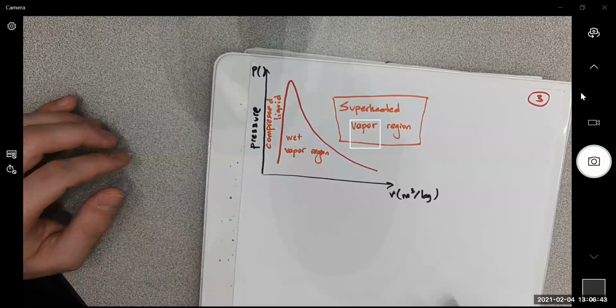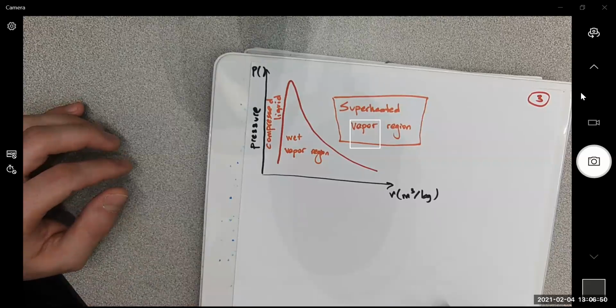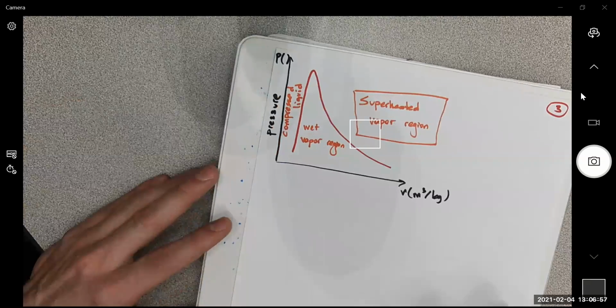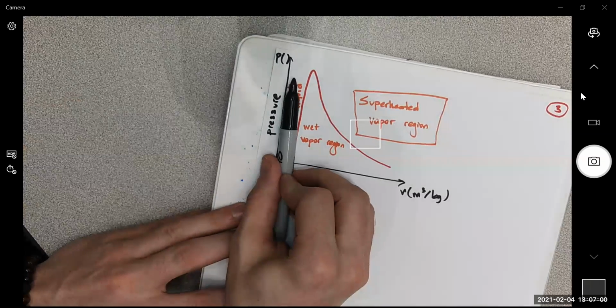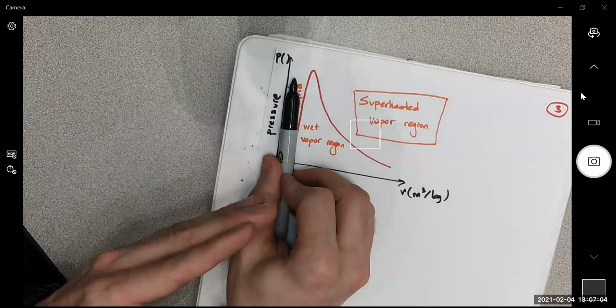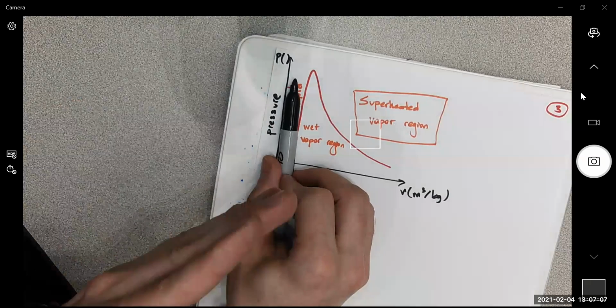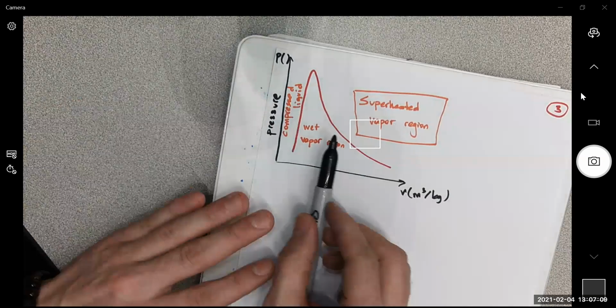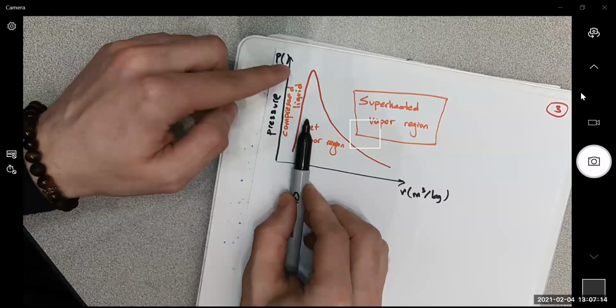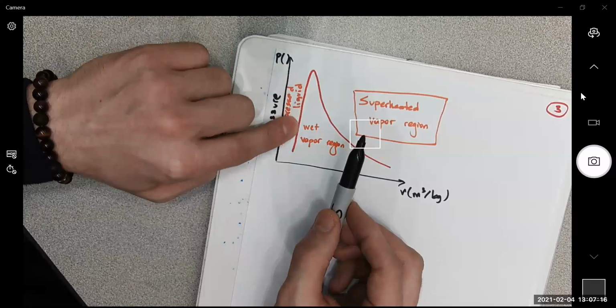So when comparing that with the linear lines that you drew, I'm guessing that the critical point represents a phase change, or is that what the critical point represents? We started that experiment in the compressed liquid region, where we have everything liquid, right? And we increase the temperature, and we got closer and closer to vapor phase. So this line is the saturated liquid line.